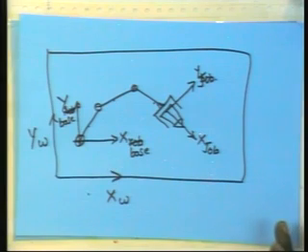See, on a shop floor, on the table where objects are kept and there is no robot there, you want to install a robot, you want to know where the objects are. In all probability, the worker will read drawings and say these objects are going to be placed here, here, here. Essentially he is giving you information in the world coordinate system, whereas the robot requires information in the robot coordinate system in order to approach the object, to solve the equations or whatever. Am I right? So there should be a transformation from this.